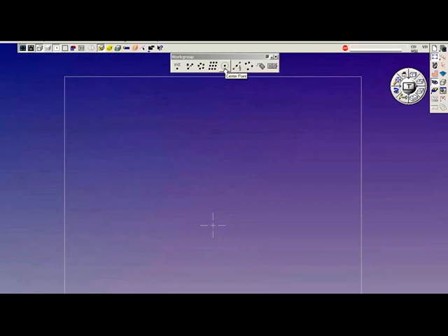And the next tile of the point subpalette is the center point tile. I'm going to go back to my first work group simply because I've got a series of points there, and it makes it easy to generate a circle where you have a pre-existing point. So I'm going to click on the circle, circle with the center point, pick a point, and generate a circle. Now, the reason I did that was just to simplify the circle creation. I'll now delete the point in the center of that circle